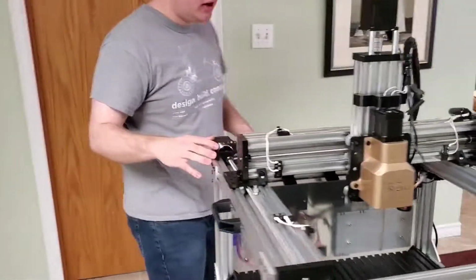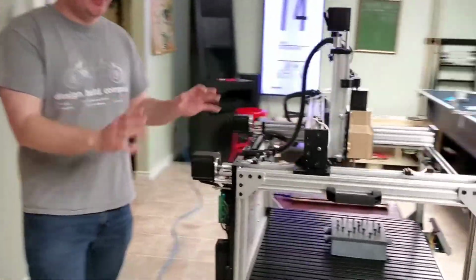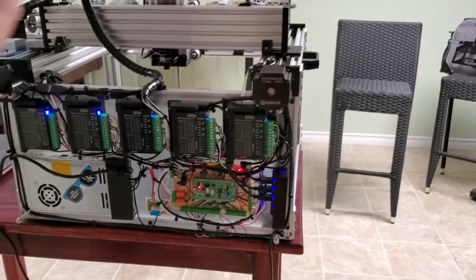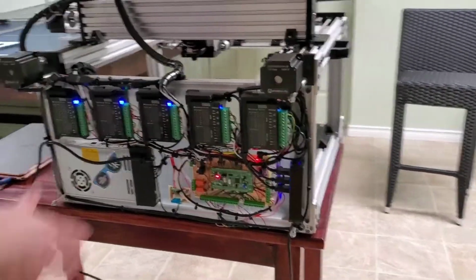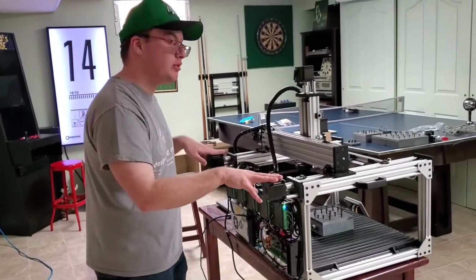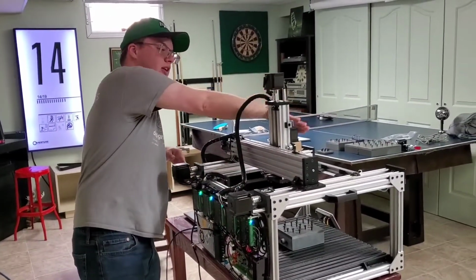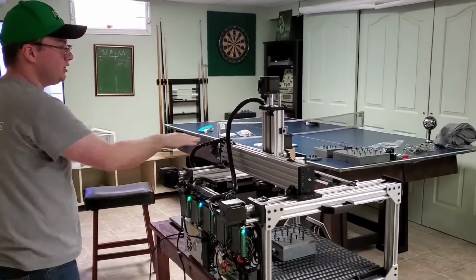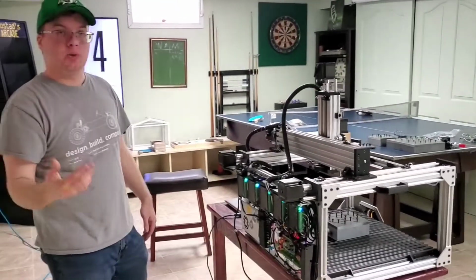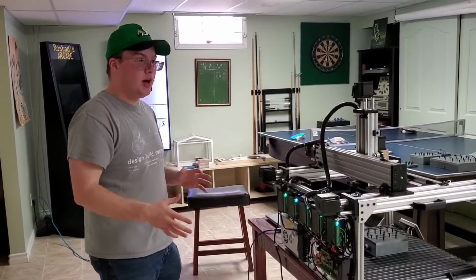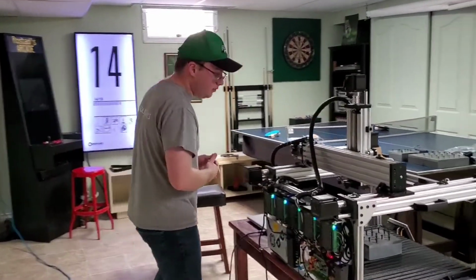Coming to the back here, we've all conveniently mounted the electronics in the back here. We'll further elaborate on that later, but effectively it's a piece of plexiglass bolted on, and then a secondary piece for protection. The motors coming off the back are NEMA 23s, while we have a NEMA 17 for the screwdriver module and a NEMA 23 for the Z and X axis. Those give us the necessary torque, which we calculated early on in the project, in order to move the machine without any binding and keep that accuracy and torque up.